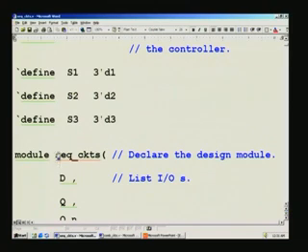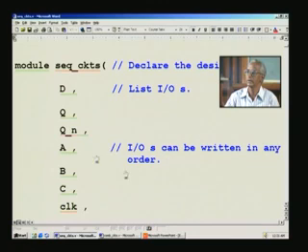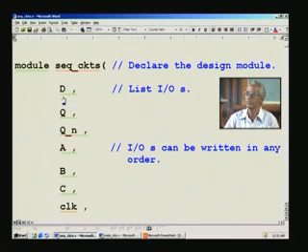And once again sequential circuit is the module name, and module is the keyword as we have seen, and we declare all the IOs, list all the IOs. As I mentioned, now the output is coming very close to this. So this time I have put all whatever functions that we have, instead of listing all the inputs and wondering to which part of the code it belongs. So it may be a good practice. If you like this, you can adopt this, right.